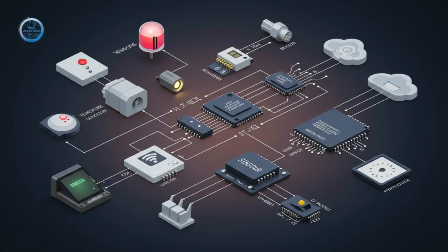This means you can get a project, blinking an LED, reading a sensor, or controlling a motor, going incredibly quickly, often without needing to understand the deep, low-level hardware details. So it lowered the barrier to entry significantly. Massively. The main limitation, though, especially for standard boards like the Uno, is that they typically lack built-in network connectivity. You often need to add extra boards called shields to give them Wi-Fi or Ethernet capabilities. Okay, great starting point, but maybe needs help connecting.